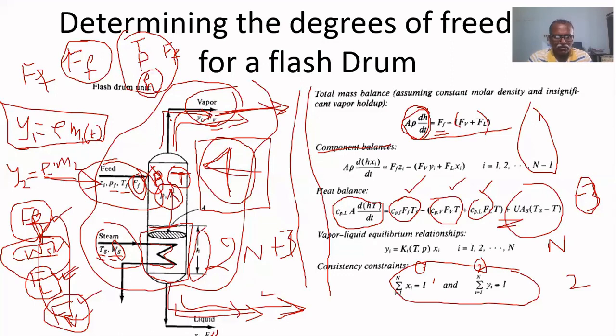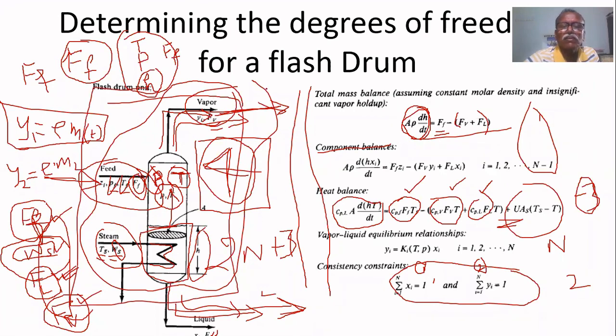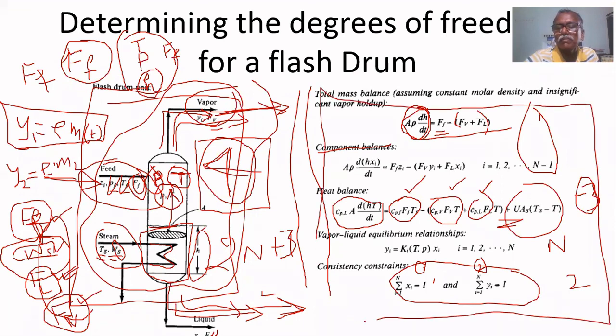First, for example, the feed flow rate, the temperature of the feed, like that. In a chemical process, what are the variables that you have to list? There is no algorithm for that. If we list out those variables, then only can we find a relation among the variables. That is called the mathematical model of the process.